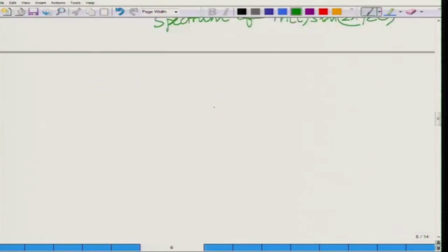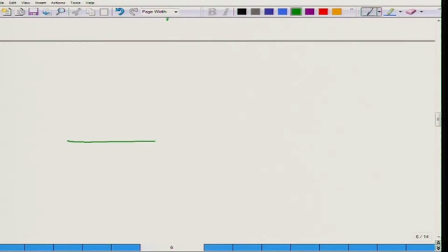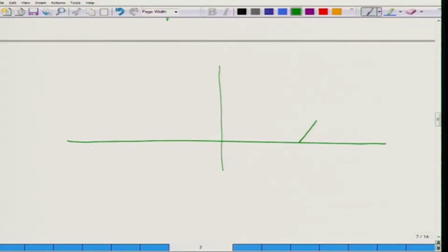So, therefore, what we are going to do now, remember, is shift this to f c. We already have positive band scaled by minus j, negative band scaled by j. Shift this to minus f c.